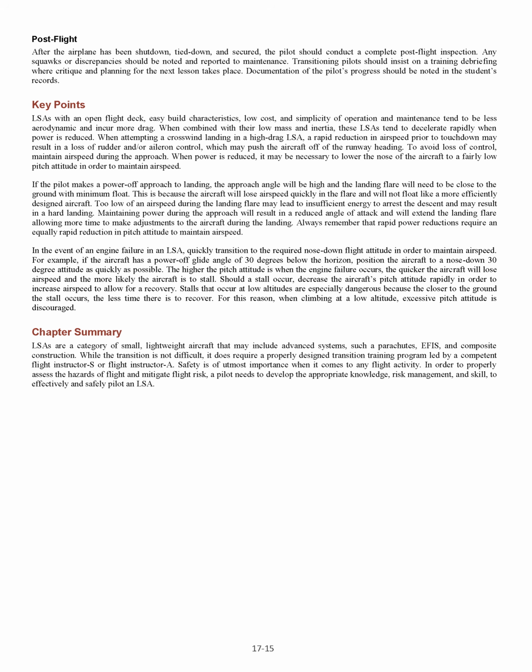Key points. LSAs with an open flight deck, easy build characteristics, low cost, and simplicity of operation and maintenance tend to be less aerodynamic and incur more drag. When combined with their low mass and inertia, these LSAs tend to decelerate rapidly when power is reduced. When attempting a crosswind landing in a high-drag LSA, a rapid reduction in airspeed prior to touchdown may result in a loss of rudder and/or aileron control, which may push the aircraft off of the runway heading. To avoid loss of control, maintain airspeed during the approach.